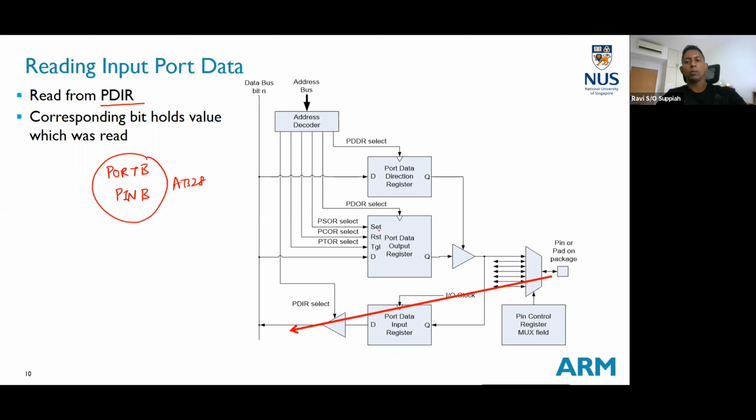Similarly over here, you also have a separate register for output and a separate register for input. So if I were to connect the pin as an input switch, then I will read the port D input register in this case.